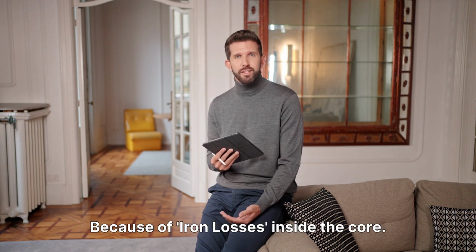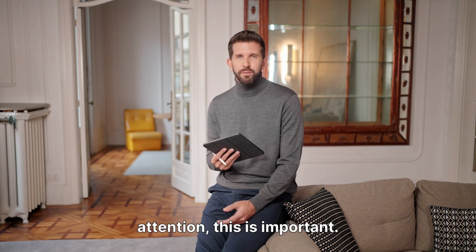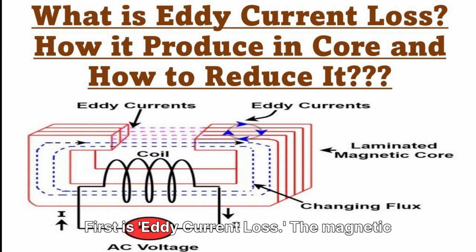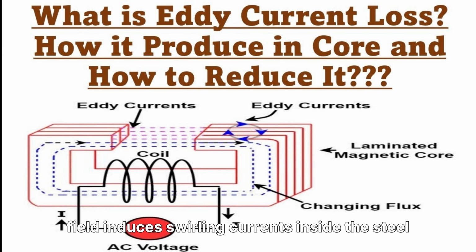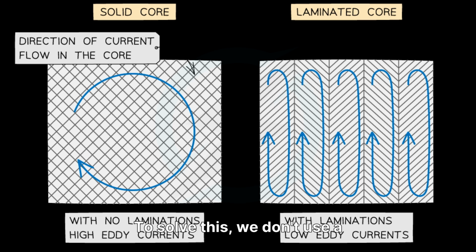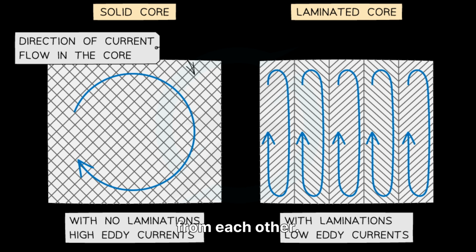Transformers get hot. Why? Because of iron losses inside the core. If you're an engineering student, pay attention, this is important. There are two main types of losses. First is eddy current loss. The magnetic field induces swirling currents inside the steel core itself, which creates heat. To solve this, we don't use a solid block of steel. We use laminations, thin sheets of steel insulated from each other.